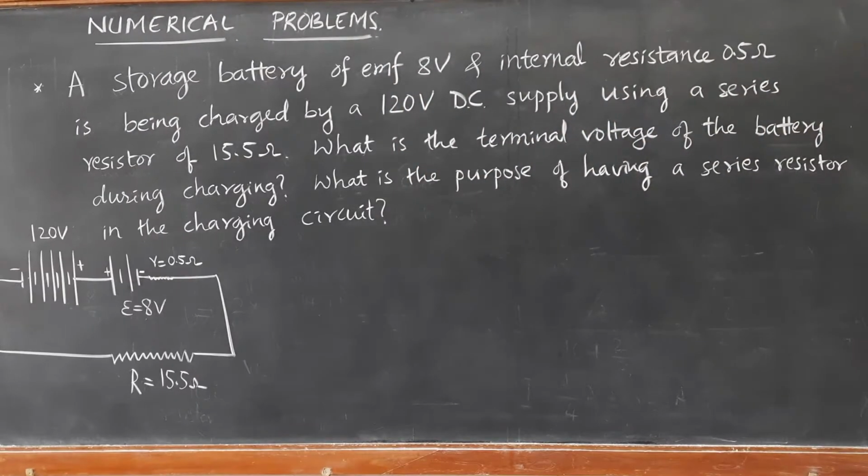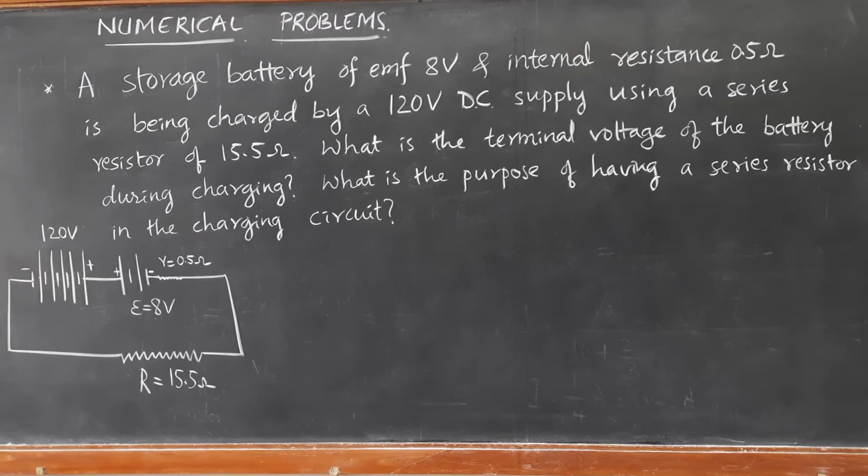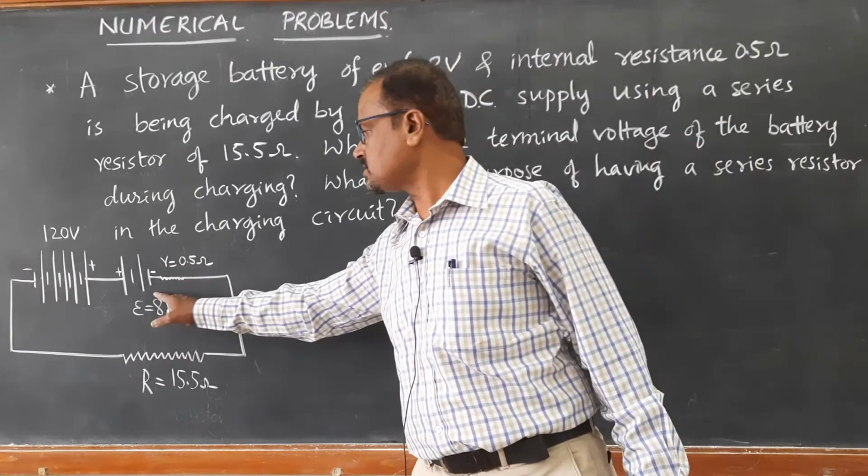Now, remember, while charging, the positive terminal of the charging unit is connected to the positive terminal of the battery to be charged.